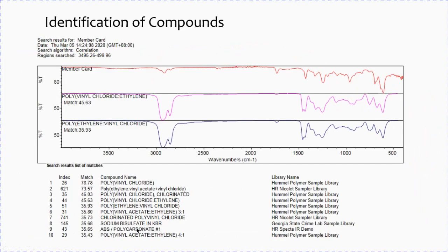The estimation using the FTIR table merely identifies the functional group rather than telling the actual compound, as one functional group could yield countless compounds, and compounds with more than one functional group might also exist. To further identify compounds, the matching of the infrared spectrum with the library database in the software has become necessary. The results show polyvinyl chloride has the highest percentage of matching. This has ascertained the fact that the main ingredient to make a magnetic stripe card is PVC.